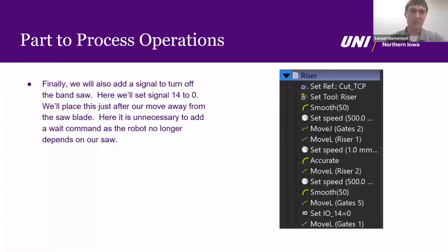There's one thing to keep in mind: when we're picking brand new locations with our robot with offline programming, those locations aren't always as well known by the robot, and you can get a lot of inaccuracy just by sending those new locations. However, by using some of these set frame locations, we actually have a much firmer knowledge of where that is in space for the robot. And so by using those locations, we reduce the inaccuracy of each of those targets relative to that location when we feed all this information to our robot when we're exporting and creating brand new programs.